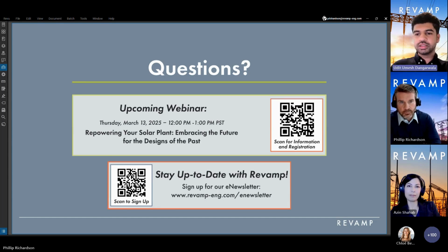Based on our last discussion, it only considers the inverter contribution up to the time when the primary fault clearing device clears the fault. So yeah, it does consider it. However, if the fault clearing time is faster than the 0.16 seconds mentioned, then it does cut off the contribution at the fault clearing time of the primary fault clearing device.